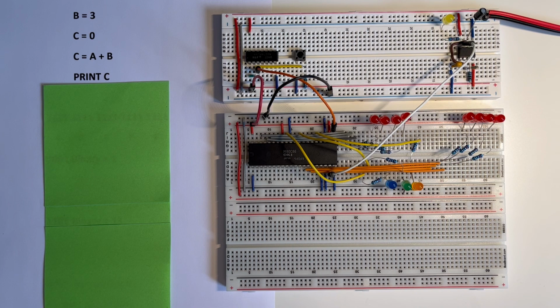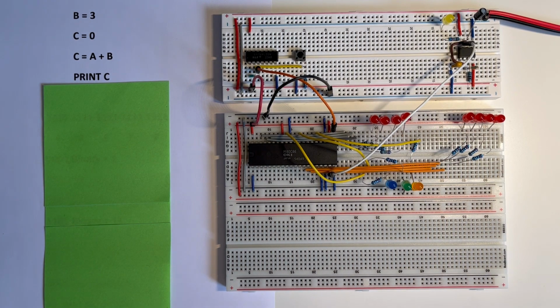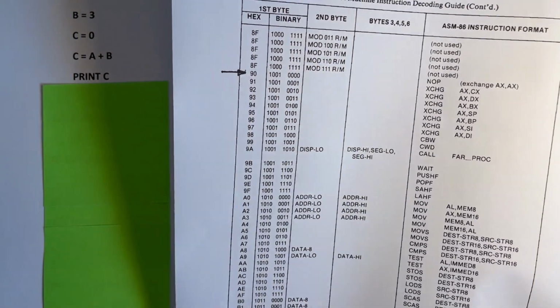Also, it has the data, and it has 16 data lines, with D0 starting at pin 16. Therefore, the processor is resetting at this address FFFF0 and is looking for the code instruction on its data lines. But at the moment, there's nothing on its data lines. So it's just reading random data. But if we could load an instruction on that data line on pins D0 to D7, then perhaps it might perform more predictably. Now here we have the instruction set.